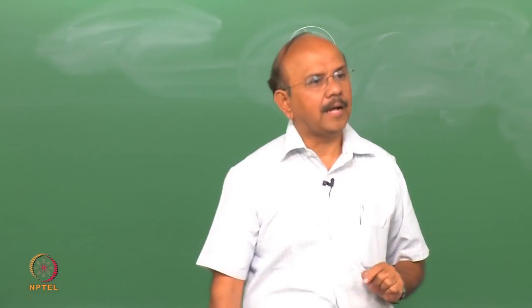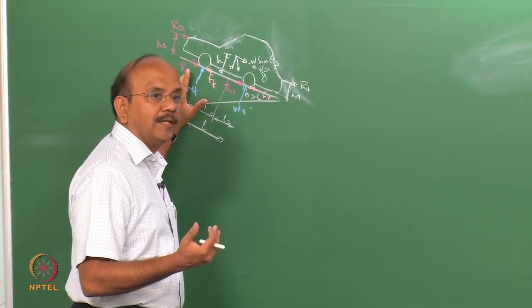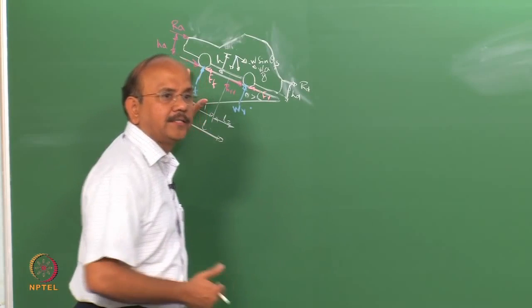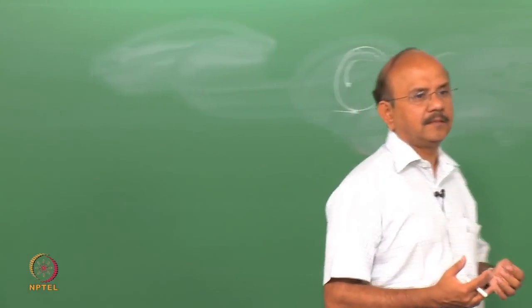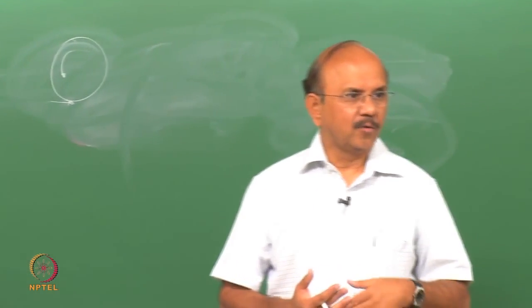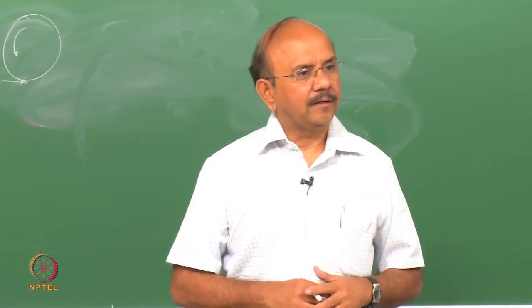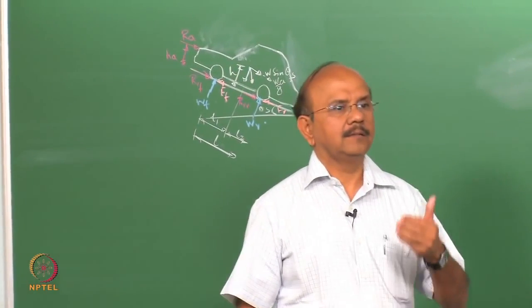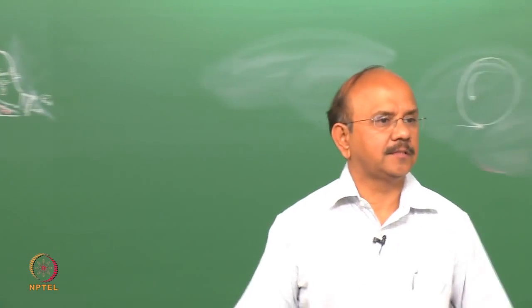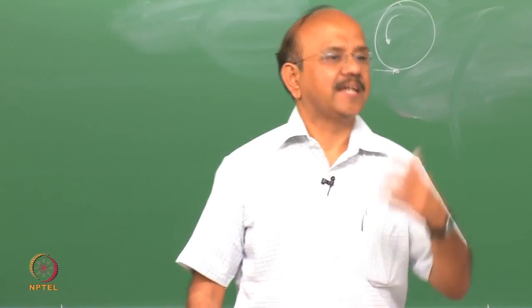So, interestingly, what really happens, which we pointed out in the last class, is that the rolling resistance is something like braking, and so helps braking when the vehicle brakes, and it decelerates the accelerating vehicle, or in other words, it is, shall we say, a bad force that's acting. Either way, since it opposes the motion, we are to compensate for this energy lost from the engine, and so it is a gas guzzler.